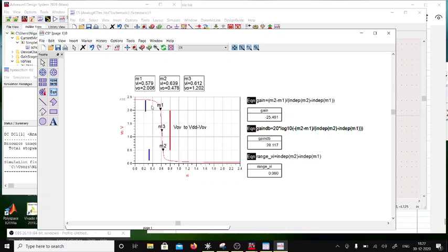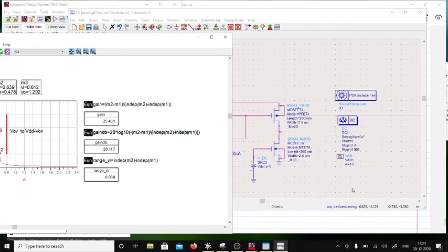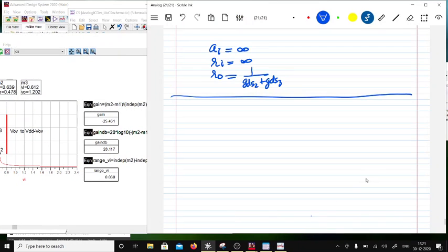And the first problem is that the V overdrive is basically limiting our swing here. That's why we had a wide swing cascode, right? Because we want to have a wide swing across the output. That's why it is called wide swing cascode, right? So that's the whole idea here. Okay, so I think you have learned a lot on the common source amplifier. Now let's just look at the synthesis part of it.